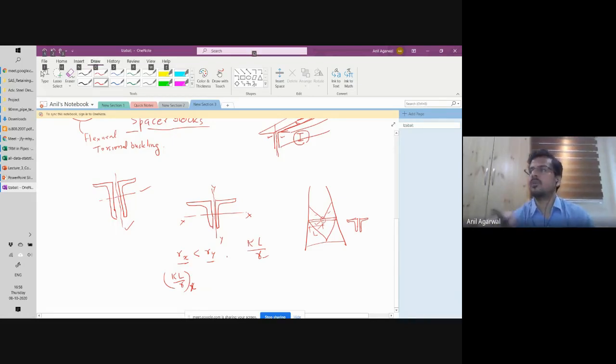And when you do the tower example, you have to be watchful for such possibilities, where a member is now adding another level of complexity here. I have to draw it in 3D, and I was dreading that. Now I'm looking at this particular cross section in 3D. So these are the 4 corners where the legs are passing. I'm not drawing those legs. This is that member, which is a double angle member. Now I had shown that there are braces coming from the top and meeting here, right? But you may also have a possibility that you have braces here.